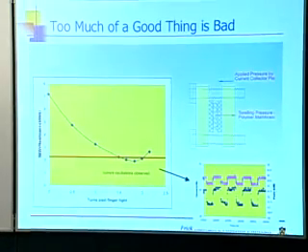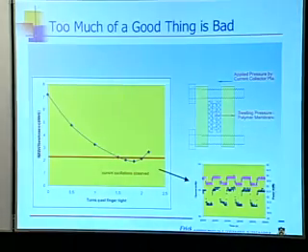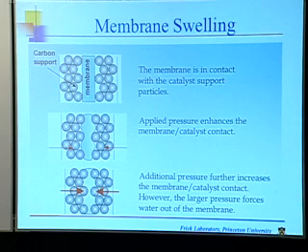And in fact, Jay has now identified, I think, 5 different steady states, depending on exactly how you assemble your cell and run it. What about how much fuel or how much current you're pulling out of your cell? Well, independent of the amount of current, you don't want it to oscillate, obviously. No. That's bad for power conditioning. But yeah, and they're pretty long periods, by the way. You probably couldn't have seen the time curve on there, but those oscillations can be over a period of an hour, type of thing. So there is an optimal tightness where you're not oscillating, but you also have optimized your membrane electrode interactions. And it's kind of interesting.